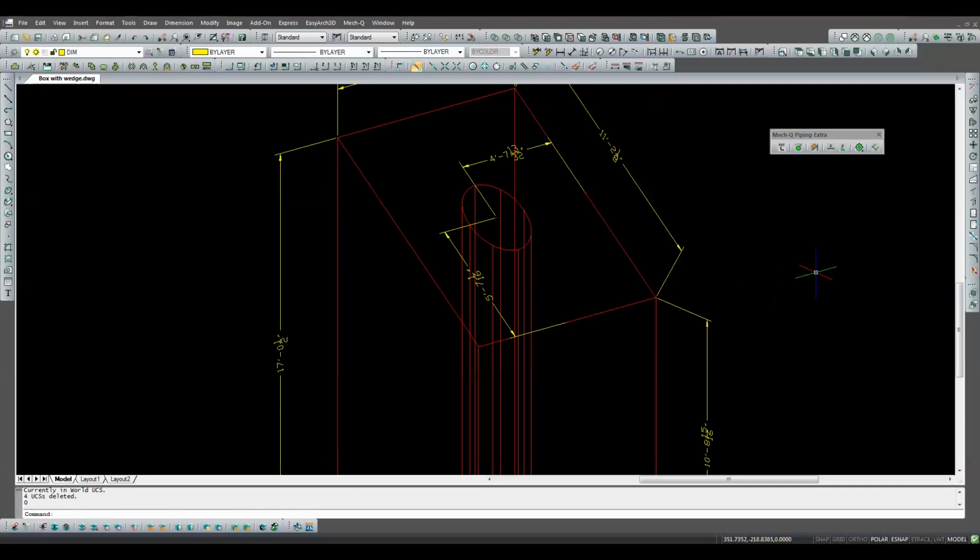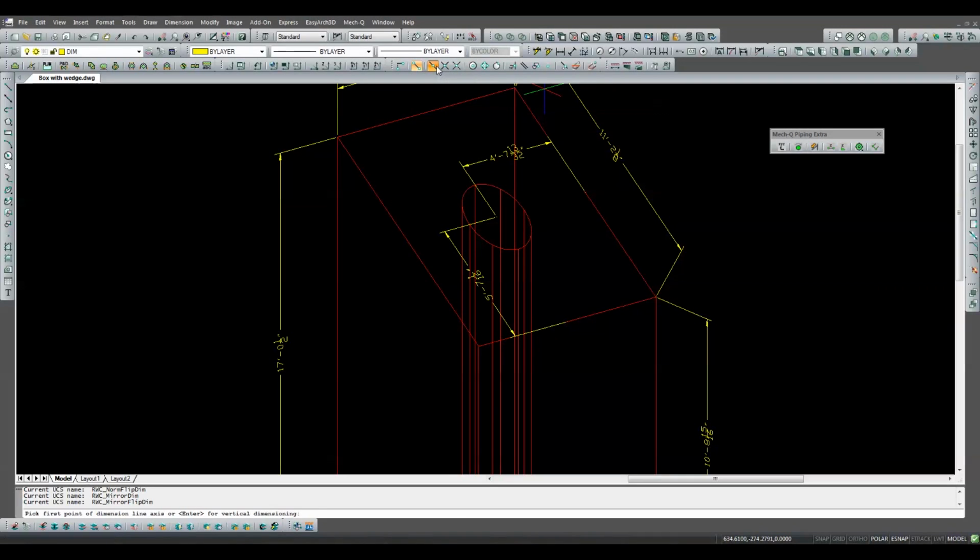One final feature we haven't explored yet is a linear align toggle. If the items to be dimensioned are not on the axis you want, simply select one point for the dimension and pull a phantom line in the direction for the other end of the dimension axis. Then select 2 points for dimensioning and the point for the dimension line. Adjust the dimension text and orientation, then simply enter L on the command line to toggle between linear dimension and an aligned dimension. When you're satisfied with the dimension, press Enter and you're finished.